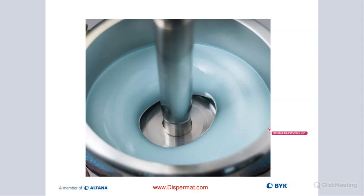And if the viscosity is too high, then you probably won't see a donut either, because the blade would spin in there and it just never really gets to form the donut because it's so thick. So this really is an optimized dispersion batch, somewhere around 3,000 to 5,000 centipoise, and if I'm running between 18 to 25 meters per second, that beautiful donut would show up. So that's what you really want to see.